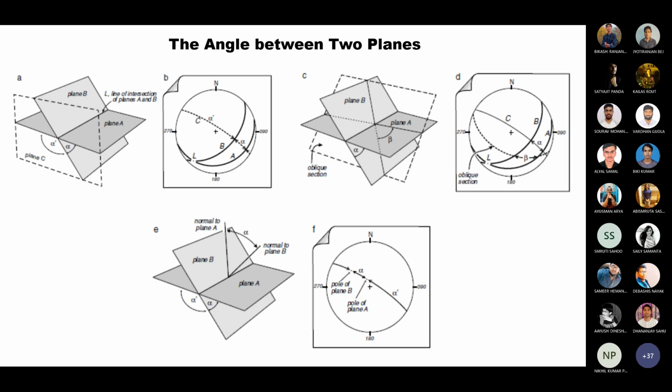Fine. So in this way, you can measure the dihedral angle between a pair of planes graphically. You should remember that there are two angles that can be measured at this stage, which can be labeled alpha and alpha naught. These are the acute and obtuse dihedral angles respectively between the pair of planes, and if you add these two angles up, they give the value 180 degrees.